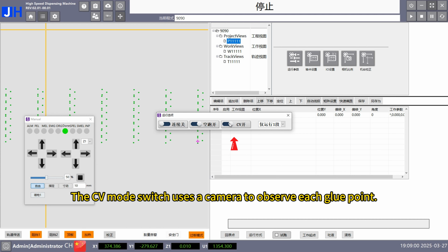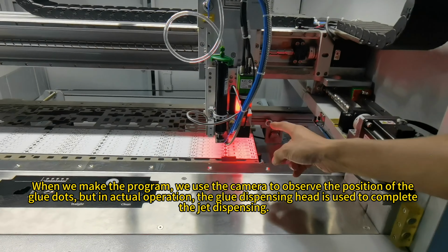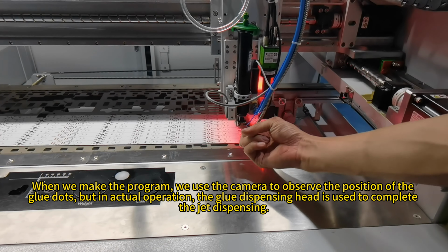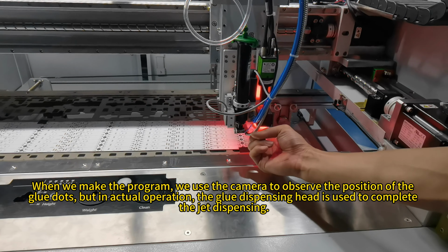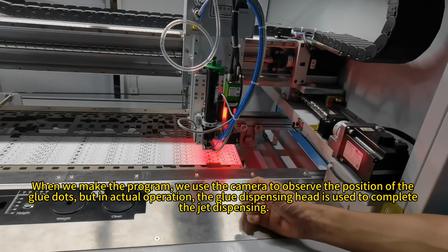The CV mode switch uses a camera to observe each glue point. When we click Run, it is the camera that observes the glue dots, not the nozzle that moves to each glue spraying point. When we make the program, we use the camera to observe the position of the glue dots, but in actual operation, the glue dispensing head is used to complete the jet dispensing.